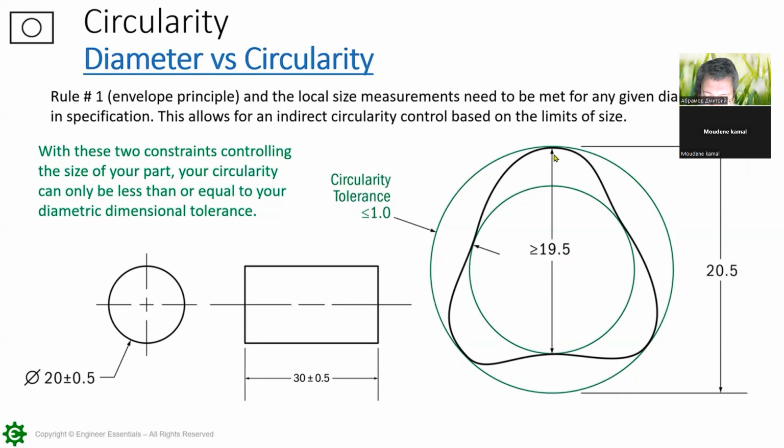We have a maximum material condition boundary, right? We can set a gauge diameter for that. And in our course, we tell you to measure the LMC. And those are our 2-point measurements that must pass, right? Nothing can be smaller than LMC, which is what they're showing right here. Nothing can be smaller than LMC for this, no 2-point measurement. And then nothing can be greater than maximum material condition with this external feature, meaning nothing can go beyond the envelope of 20.5.